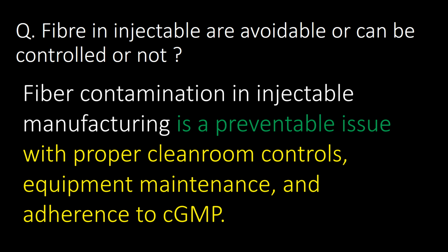Very important question, are fibers in injectables avoidable, or can they be controlled or not? Fiber contamination in injectable manufacturing is a preventable issue with proper cleanroom controls, equipment maintenance, and adherence to CGMP.